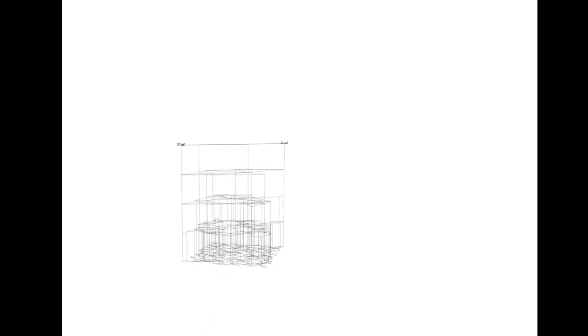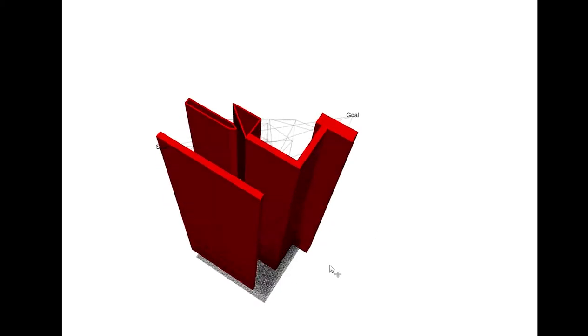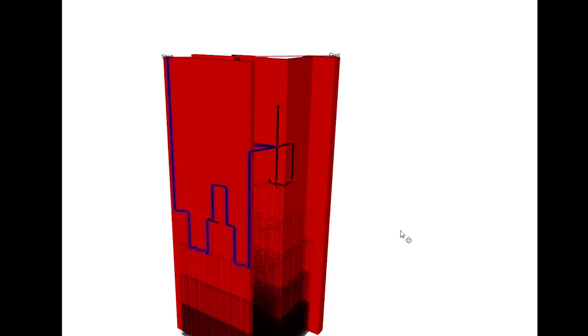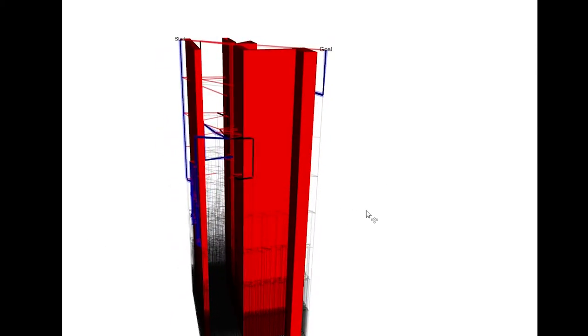Remember, this graph represents a 2D roadmap, so the vertical edges here do not correspond to any robot motion. Obstacles block the same configurations in all layers. We find a path using a heuristic search, checking edge validity online. Our heuristic has an inflation factor that gets larger as layer depth increases. This guides the search to expand nodes that are both close to the goal and on the sparse layers that